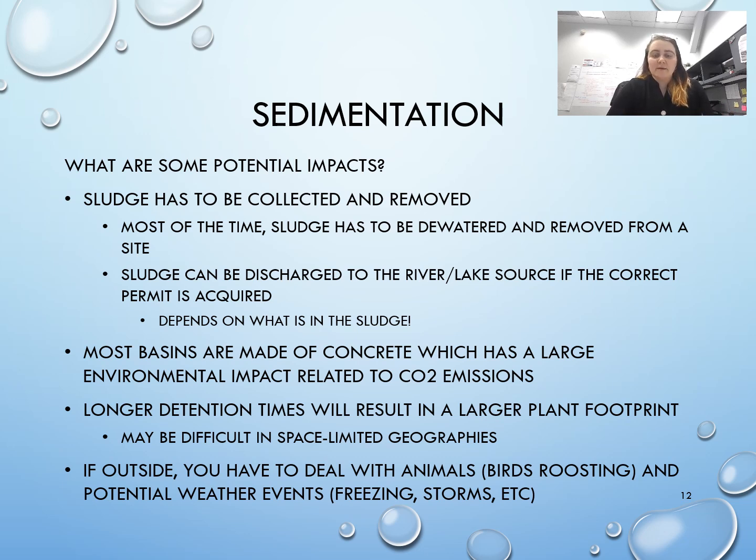Longer detention times are going to result in a larger plant footprint. Again, sedimentation basins are generally pretty big, and this may be very difficult if you're in a space-limited geography. If you are in the mountains in Colorado, it's probably going to be pretty difficult to get a big sedimentation basin. So you're going to have to be careful about where you locate your treatment plant if sedimentation is part of that process.